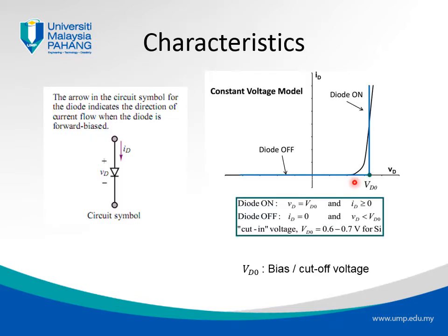So from that explanation of the basics of the PN junction and the behavior of that PN junction that creates that bias voltage, we can therefore deduce a characteristic of a diode. So here we have a symbol of a diode. The anode is noted as the positive terminal and the cathode as the negative terminal, and we show the direction in which it is forward biased by the direction of the arrow, where it will conduct current in this direction and not in the opposite direction.